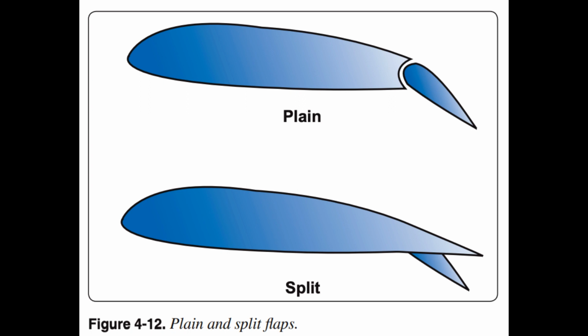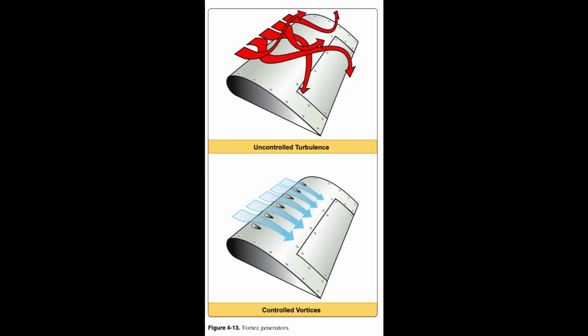However, the value of lift, flaps extended to the CLmax position, produces more lift than lift at 18 degrees on the basic wing. Delaying the boundary layer separation is another way to increase CLmax. Several methods are employed, such as suction and use of a blowing boundary layer control, but the most common device used on general aviation light aircraft is the vortex generator. Small strips of metal placed along the wing, usually in front of the control surfaces, create turbulence. The turbulence in turn mixes high-energy air from outside the boundary layer with boundary layer air. The effect is similar to other boundary layer devices. Figure 4.13, Small airplanes.